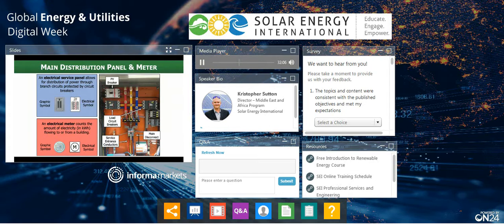There is metering or measurement right in the middle. We have two big load circuit breakers that split off to two sub-distribution panels. And then on the top, we have a PV circuit breaker that ties in. So the PV and the utility all meet on the same bus bar and match voltage and frequency automatically by the inverter. So that point of interconnection with the utility is actually not very complicated because it just synchronizes and connects to the distribution through a normal circuit breaker.